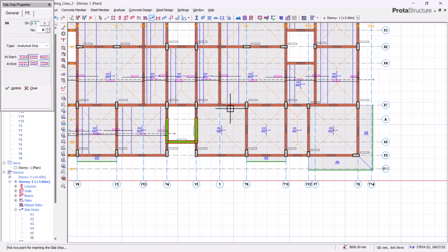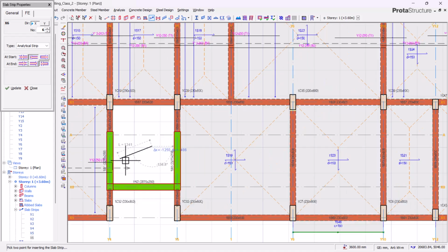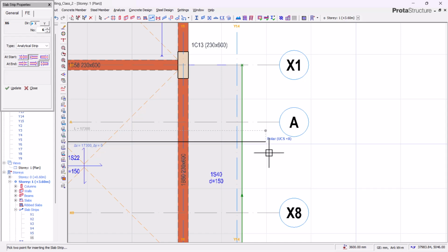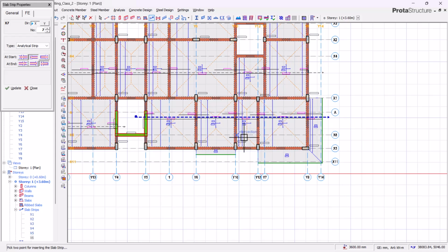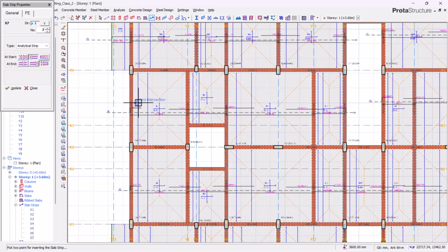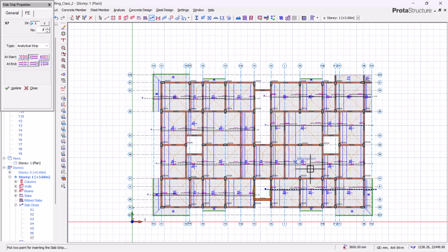We've already run our slab strip on this panel earlier, and the last one is coming from a bob and ending at a cantilever. So we'll click here, and we take it to our cantilever. All right, so we are done with it. It has provided both our top bar and our bottom bars, and they are mostly Y12 at 250 spacing. The next thing is we also run our strip, because running your strip for the x-axis is not enough. You also have to run for the y-axis.